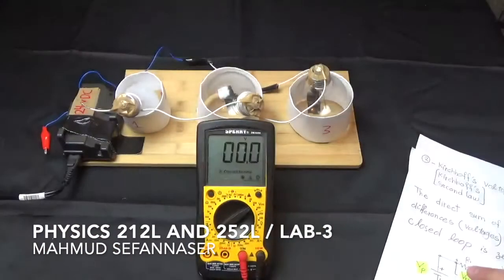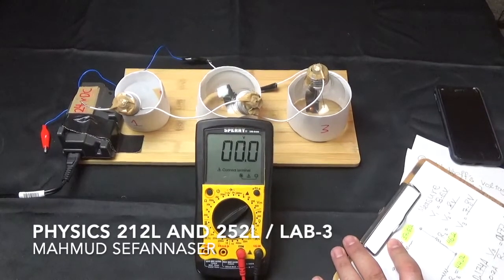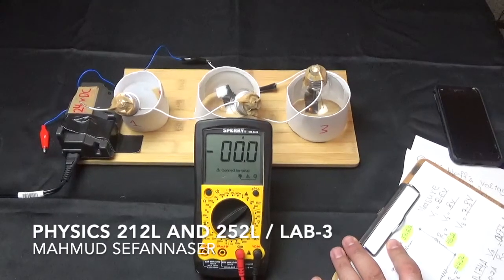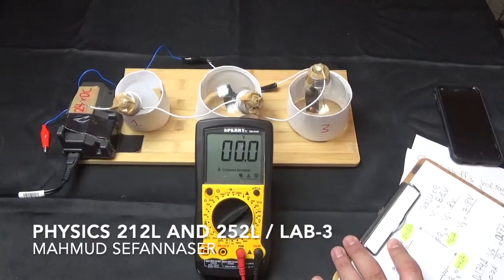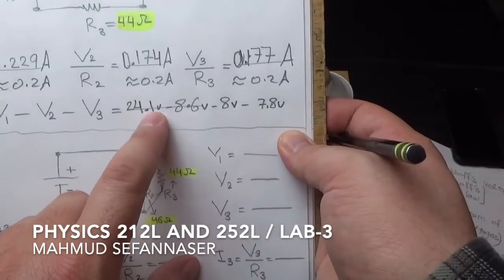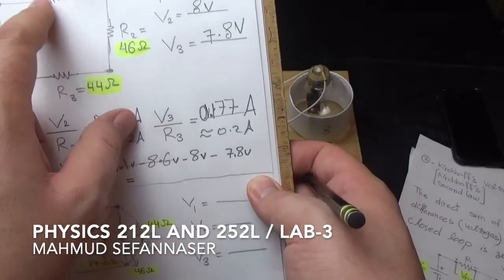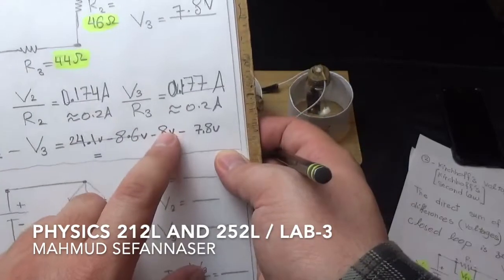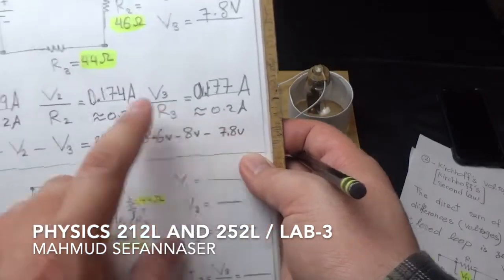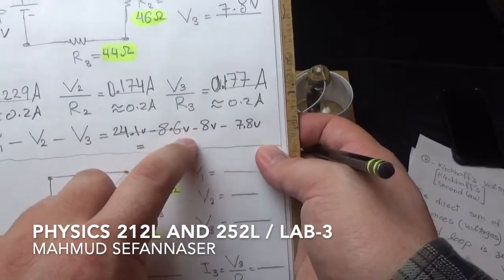So that's 24.1 volt, which is the power supply voltage, minus 8.6 volt, which is the voltage across R1, then 8 volt, which is the voltage across R2, and then 7.8 volt, which is the voltage across R3. Now let's calculate that, guys, and see what do we have here.